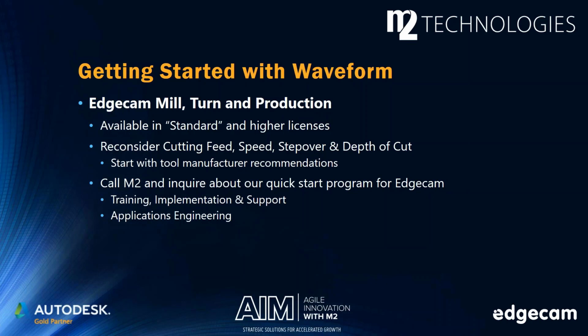If you do not change the speeds and feeds for what you're used to doing, you'll experience that waveform, because it builds more path, because its more intelligent path is going to take longer to run. So you really want to reconsider your cutting parameters. In most cases, start with what your tool manufacturer recommends. Our experience is that in many cases we can cut faster, and this is true for both your off-the-shelf tools from maybe MSC, as well as engineered cutters specifically recommended for unique applications.